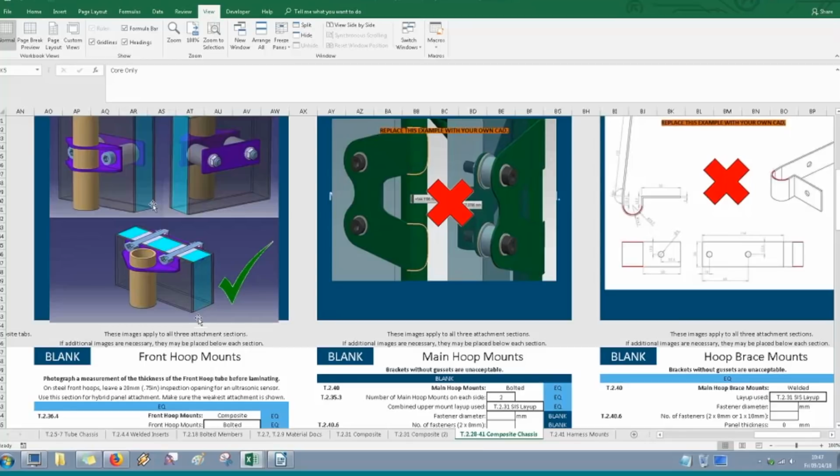And the definition of free edge is where either the composite stops, like it does right here, or if, for example, this was a side impact and the floor went off here and you had this corner, it would come out the corner. It would not turn around the corner and keep going around the floor. So that's going to be your free edge distance. It's to either the nearest end of the composite or to where the monocoque structure turns a corner.